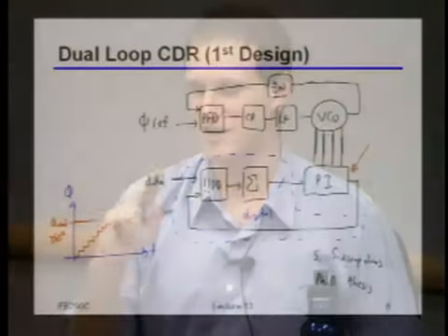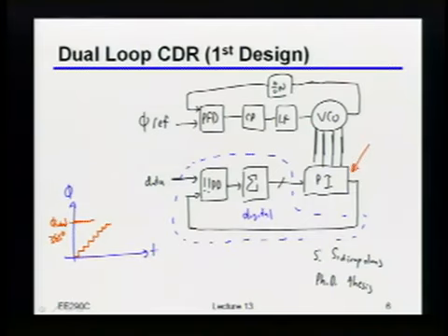But notice, all I'm doing here to generate the delay is just interpolating between clocks, right? I'm just interpolating between clock phases. So if I want 365 degrees of phase shift, what is that equivalent to? 1 period. 5 degrees. It's equivalent to 5 degrees, right? So if I want 5 degrees, then all I do is I just allow this code to wrap over and choose 5 degrees instead of 360, right? So in other words, what I'm getting at here is that if you've done this system right, where you actually allow yourself to just spin that phase code all the way around the circle, you can actually get infinite phase capture range.